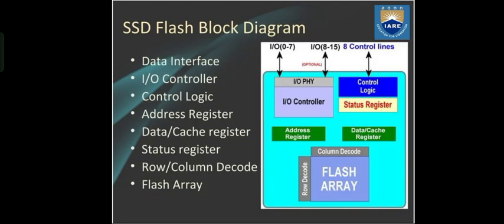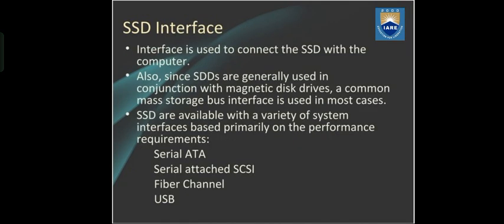SSD flash block diagram. It contains data interface, IO controller, control logic, address register, data cache register, status register, row column decoder, and flash array, as you can see on the screen. SSD interface.